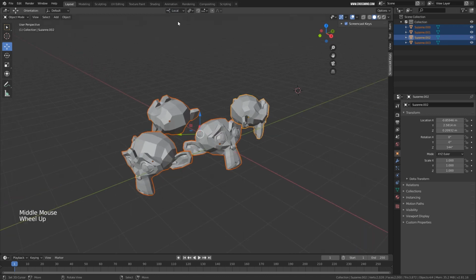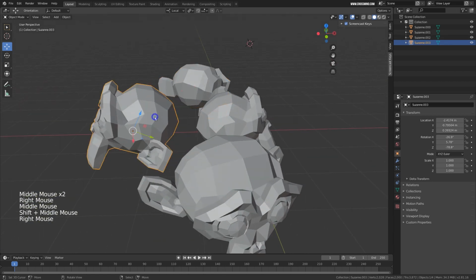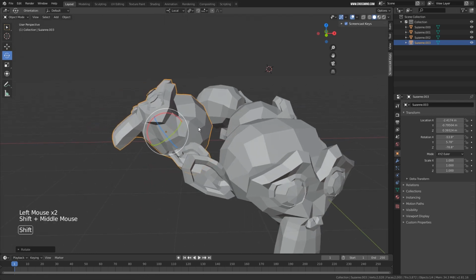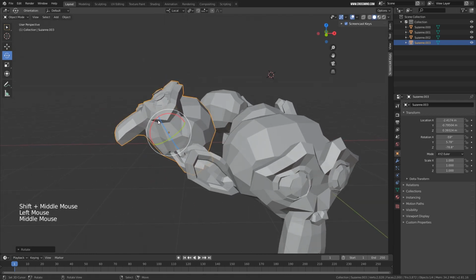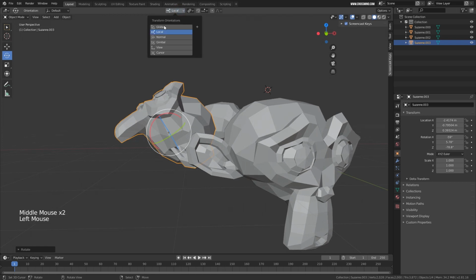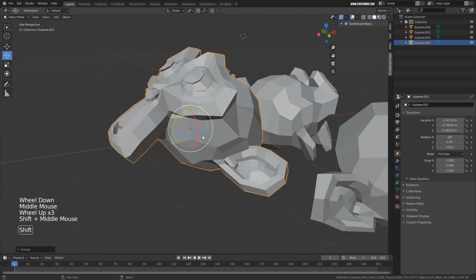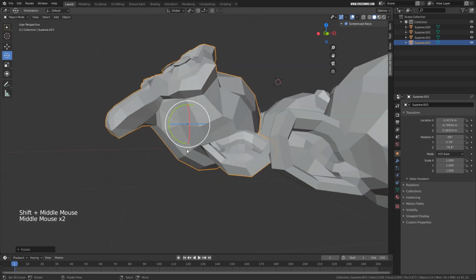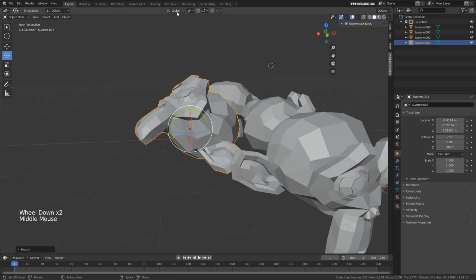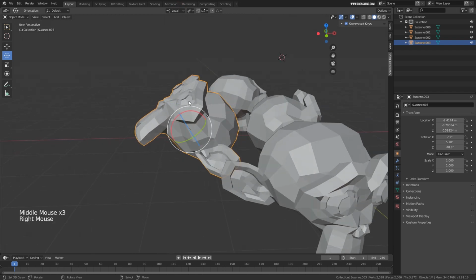Now what this means is, if you select anything, let's select this object, and change this rotation, now you'll see the z direction is tilted upwards. This is not parallel to the world z direction. If you change this to global, you see the gizmo is showing a line parallel with the grid. That is because we are using the global coordinates. If I change this to local, this will switch to this direction because we made some rotation in this model.